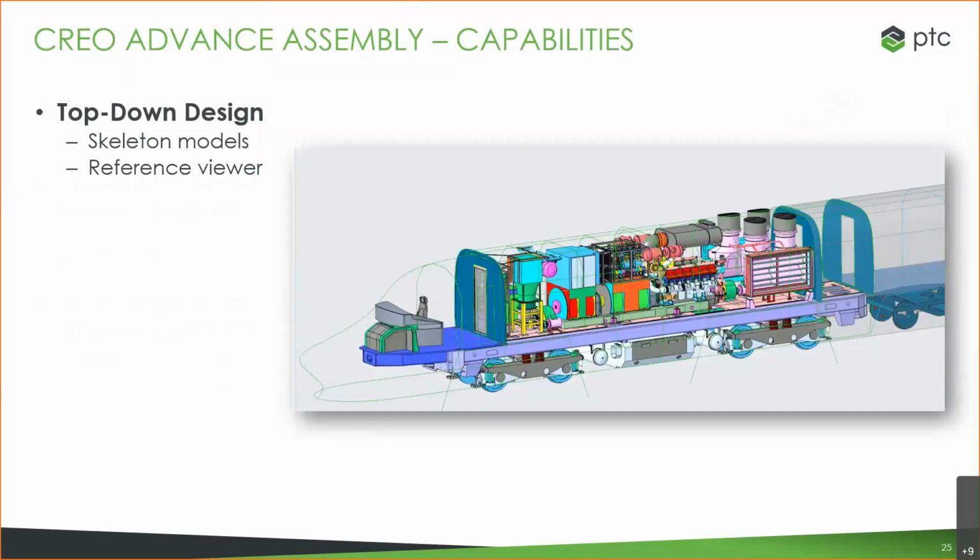So you need to be able to look at the model and understand how these pieces go together, how they're related, and then you're able to understand how to best share or change your assemblies depending on what it is that you're doing. You also have reference control. So it's very easy to define best practices to manage and limit assembly component references, which is a really big deal when working with large assemblies, or even, maybe not even large assemblies, just assemblies that are possibly going to be changed later on. To have a flexible assembly is really important to be agile and flexible in your product, and reference control is a really big part of that.